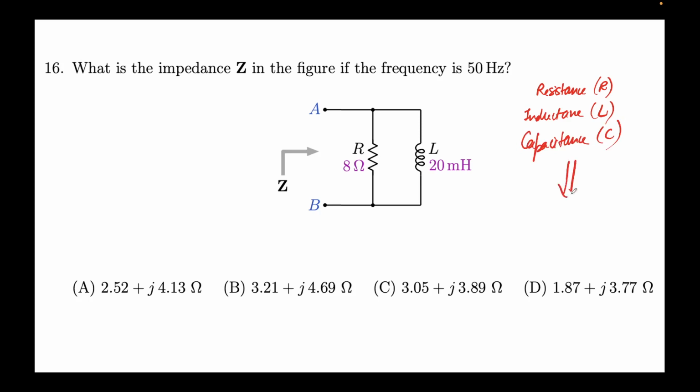When working in the frequency domain, the underlying electrical characteristics remain the same, but the way we denote them becomes different. So here we denote it as ZR. That will be equal to R plus j0. So this is the real part, this is the imaginary part. So there is no imaginary part associated with the resistor. So ZR equals whatever the value R is plus j into 0. You can say this is purely real.